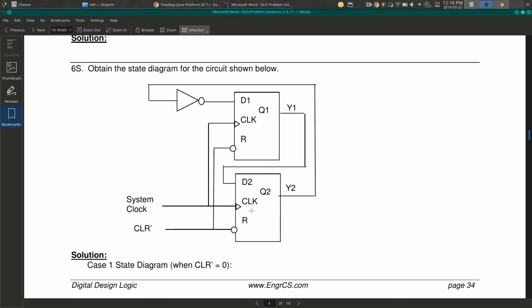But here's a way you can figure this out. You can only have one output driving things. You can't have outputs connected together. Okay? You can have one thing feeding multiple inputs, but you can't have an output with something else driving that output.